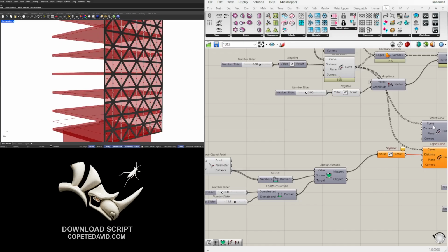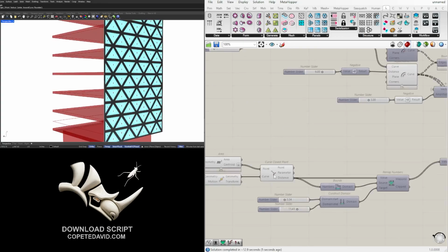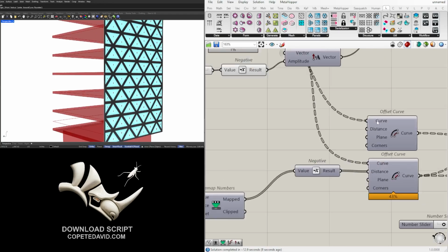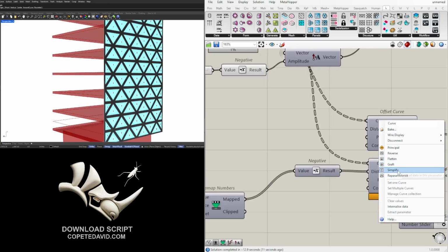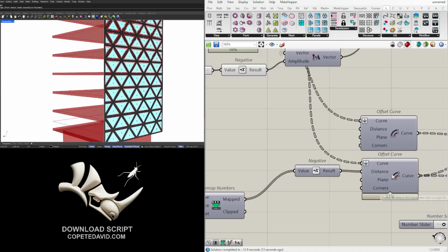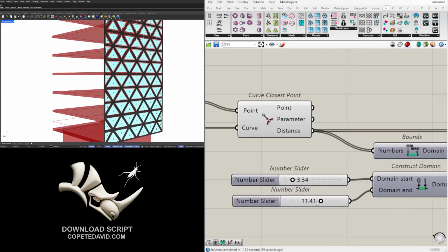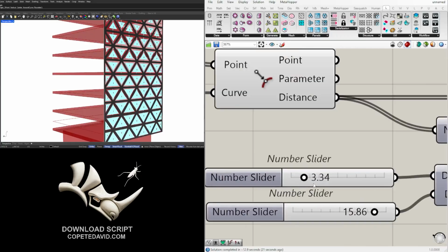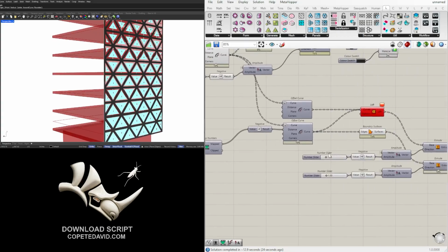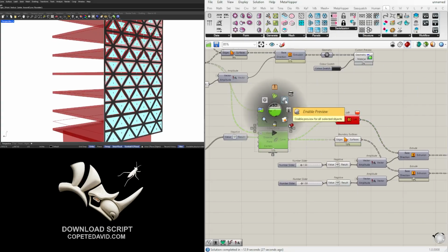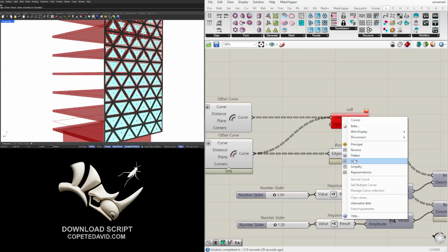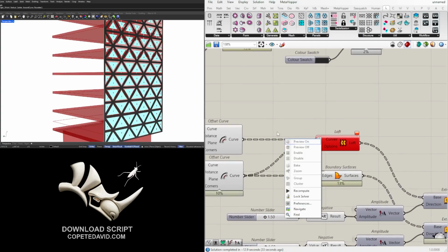The other thing is that these are grafted sets. So we need to make sure that these are going to be flattened and these are going to be flattened. So since that was flattened, we'll do that to this one. And we'll do that to this one. So now let's change the maximum here, the minimum here. But on this input, we will graft them here.